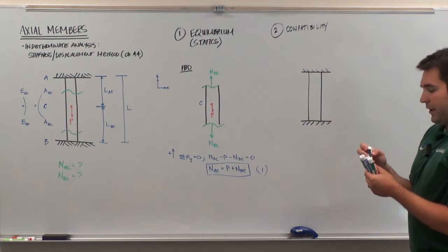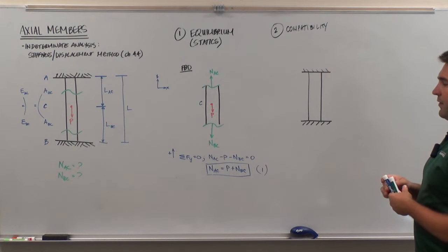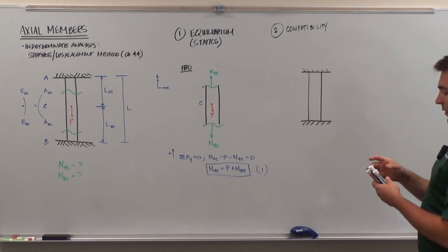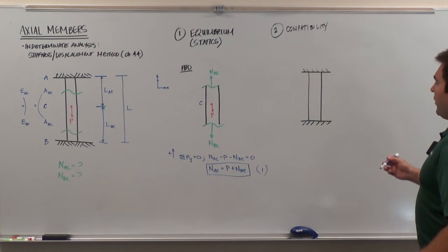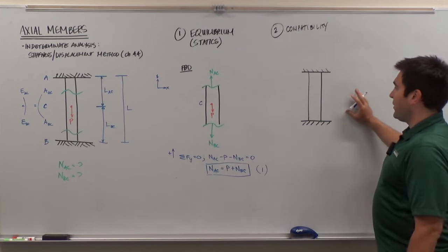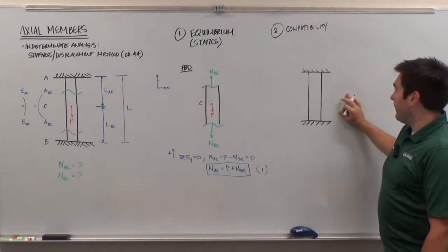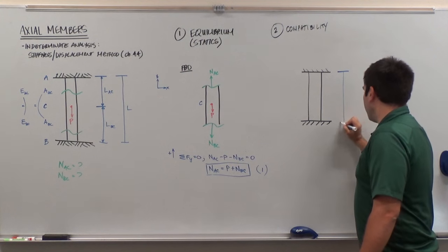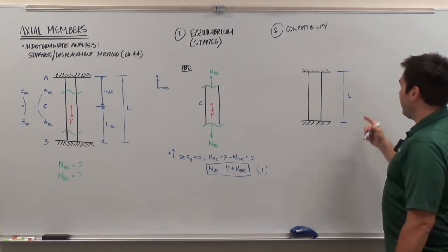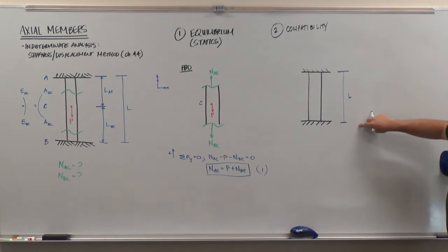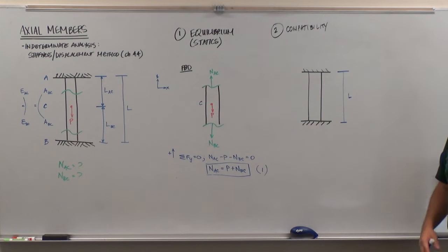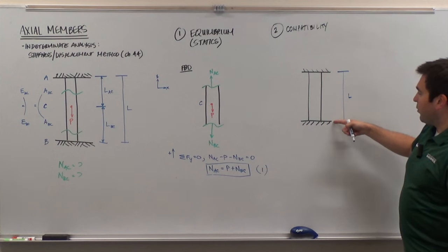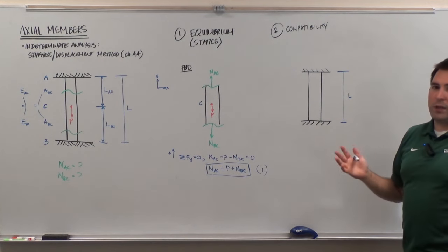And you don't even technically need to draw the displacements on there. So you don't need to draw the force on there. We can just start looking at the displacements. And so here, there's a couple different ways to get this step done correctly. One, the most important thing that we know here is that this overall length between the fixed supports can't change. This is a rigid support, this is a rigid support, so the overall length can't change.